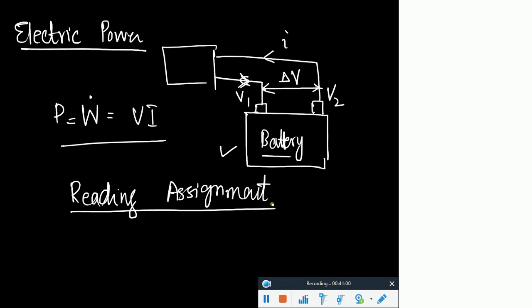I can just tell you that if you are talking about rotary systems, you deal with torque instead of force, right? And instead of translational velocity, you would be dealing with angular velocity, right? Although there is a theoretical foundation as well, in that case the power transmitted, or the rate of work done by the motor on the fan blade, would be torque multiplied by omega, that angular velocity. You can go back and see how to derive it. But my purpose is just to give you a few examples of the representation of work done in different systems in their mathematical form.